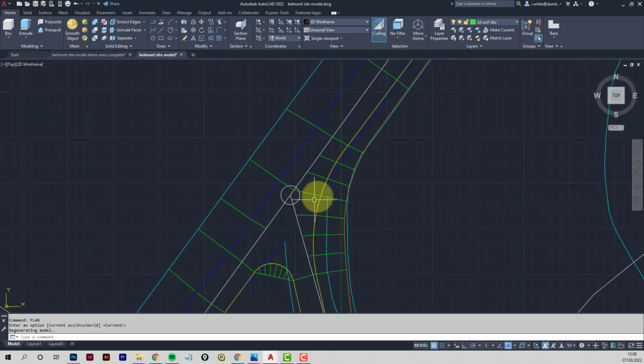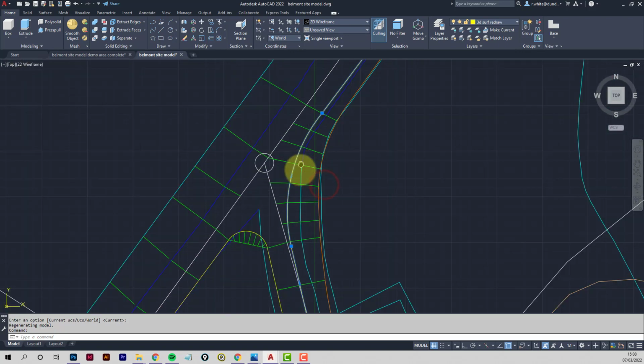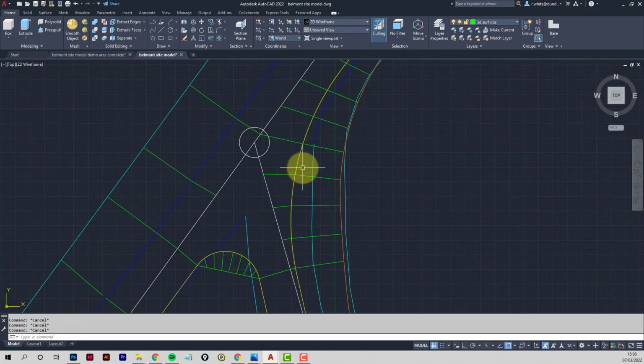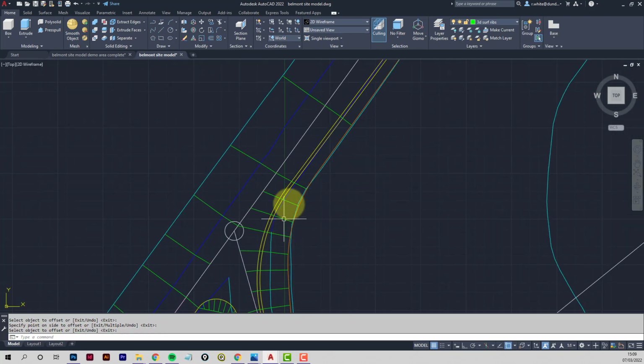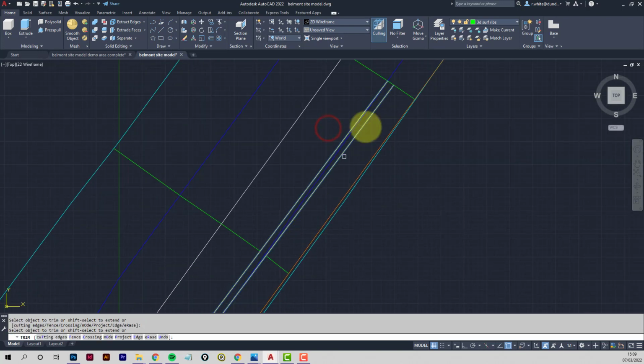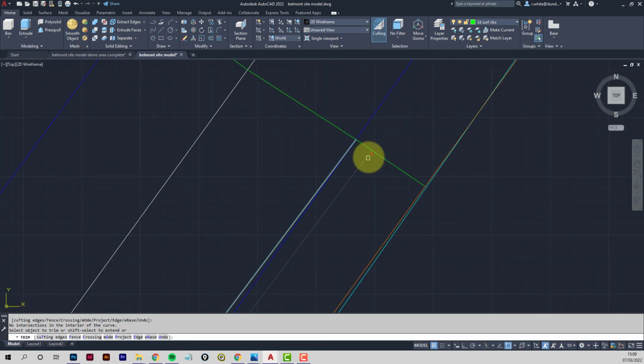okay, let's take this yellow one to start off with. That's down at level 0, but if we offset it by, I'm using 400 millimeters here, then I can trim using both the yellow lines. I can trim away bits of the ribs.